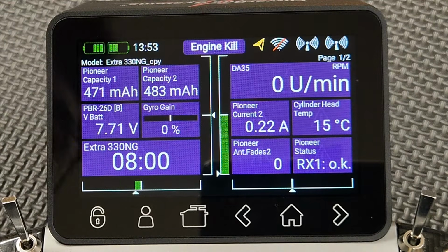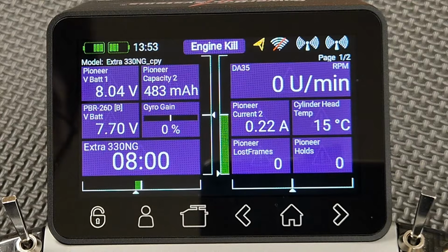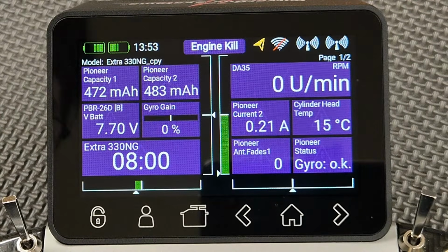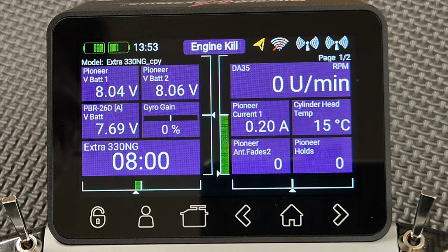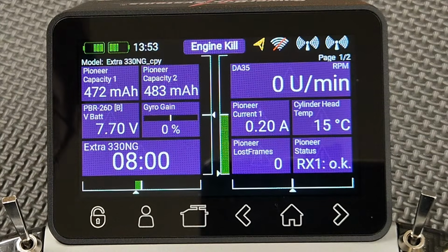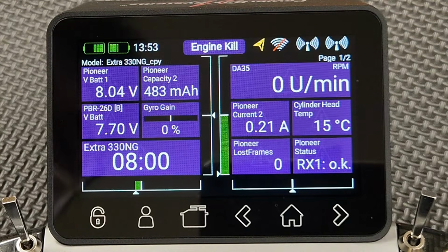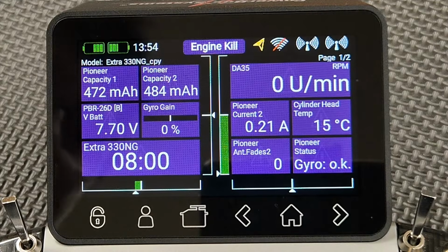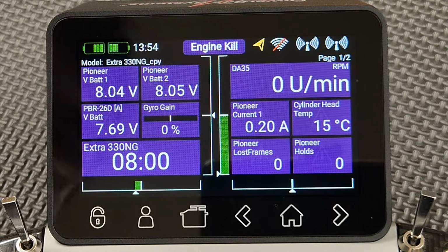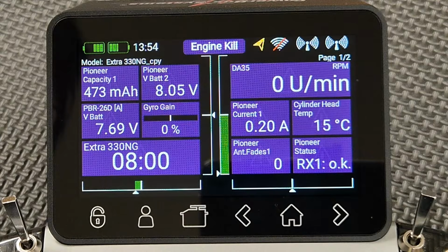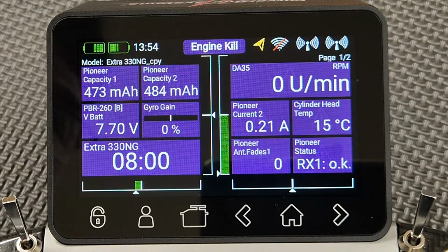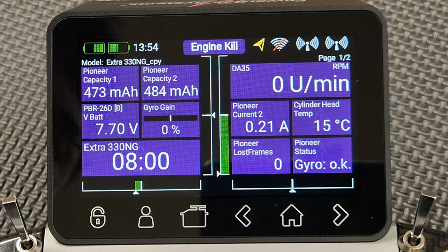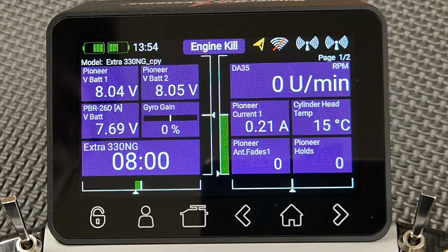But, to have an idea of how many hours your engine's been running for, you either have to keep a log of the number of flights, which is not necessarily that accurate, because you might have the engine sitting there idling in the pits for half an hour before you go take off, and you might record, say, one flight, but the engine might have been actually running for, say, 20 minutes, while the flight only took, say, 10 minutes, because it was idling in the pits. So ideally, you want a better way of taking note or accumulating the number of hours that an engine's actually been running for.